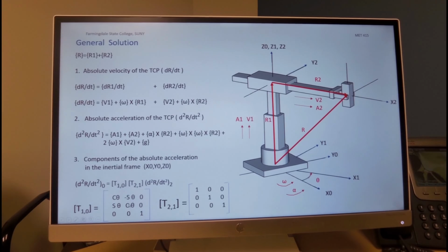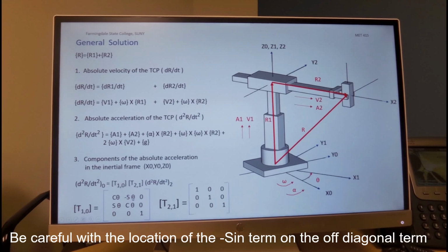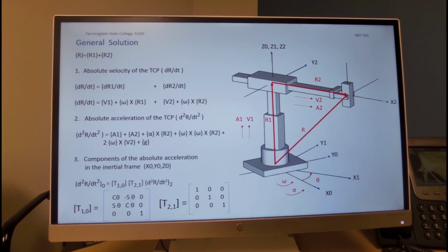However, the rotational matrix from coordinate system 1 to 0, as we found in a previous presentation, is cosine on the diagonal, 1 along the axis of rotation, which is the z. This is the position, zeros on the columns and the rows, cosines on the diagonal, and then sine off the diagonal with a minus sign that we have to check its direction, as we discussed in the previous presentation, to find out where the minus is, in this position or in this position.